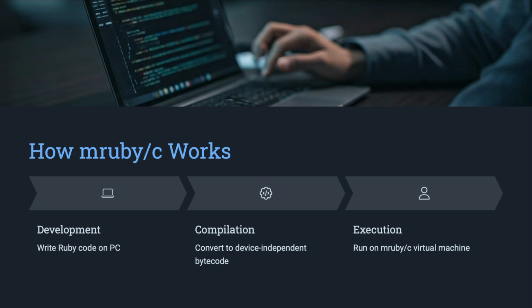Got it. So how do you actually get your program onto the chip? You don't code on the microcontroller, right? No, no. You write your Ruby code on your development PC, like usual. Then you use a compiler to turn that into device-independent bytecode. Device independent. So the same compiled code could run on different types of chips. Potentially, yes. That bytecode file is then sent over to the microcontroller itself. The microcontroller already has firmware loaded onto it, and that firmware is the mruby virtual machine. Think of it like a tiny Java virtual machine, but for this mruby bytecode. The VM executes your bytecode.